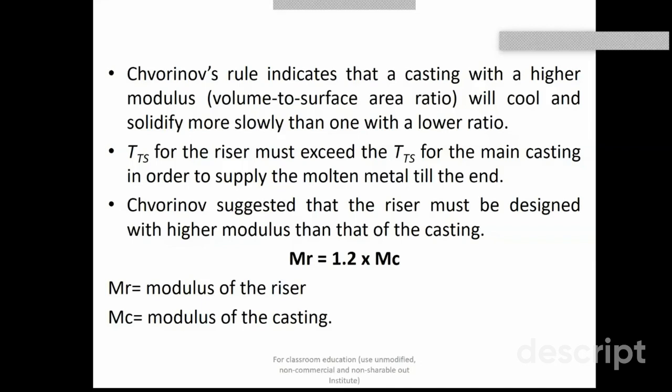However, in the case of a side riser, all of the surfaces, including the top surface, bottom surface, and the curved surface, will participate in the heat transfer. So now you have to calculate the area, and then you can minimize this area by partial differentiation. Differentiation is used to calculate the diameter, and then we have seen that in case of the side riser, the relation between the height and the diameter comes out to be h by d equals 1, and in case of the top riser this comes out to be 0.5. This is already given in the books.